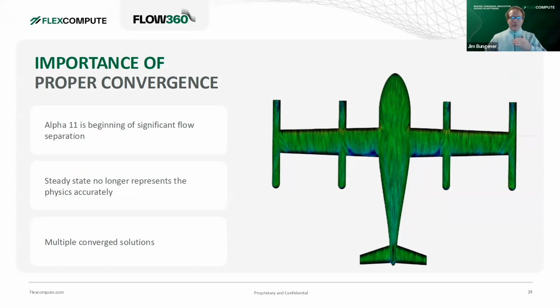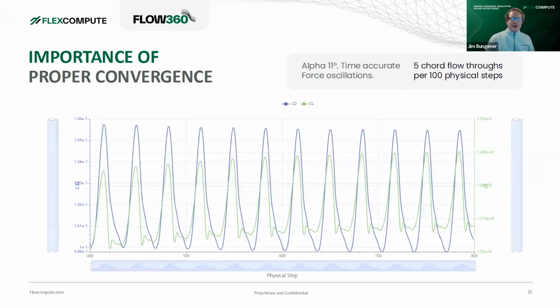And so by forcing this time varying phenomena into a steady state solution, we're not being really honest with ourselves, and we're asking too much out of that steady state simulation. And it's trying to give us the solution, knowing that there is more than one solution. So it is oscillating between these different answers. You can see it here.